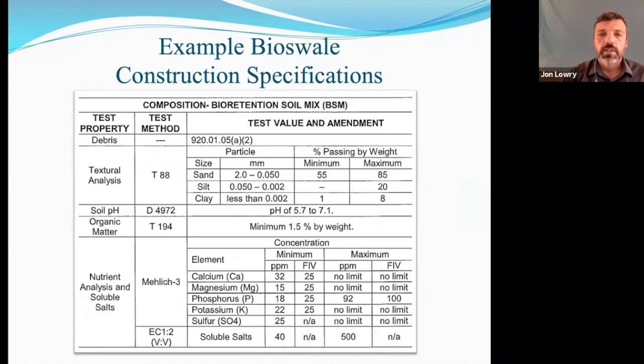engineered soils. So this is a sample specification, but it's important to us that the spec be followed, and as a contractor, you'll be asked to submit a sample and a specification sheet from wherever the source of your engineered soils is.